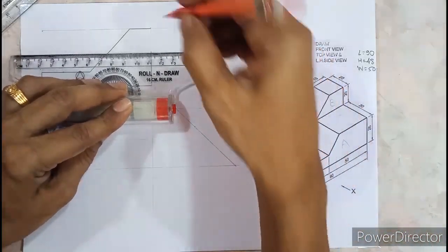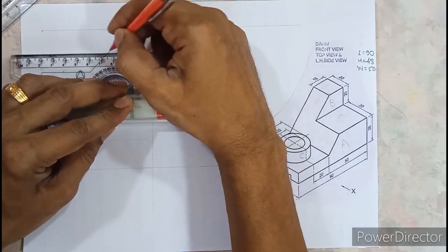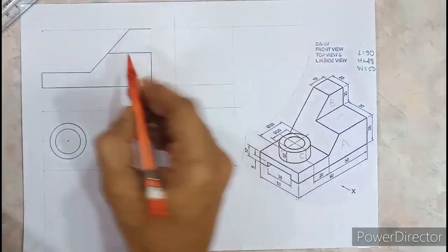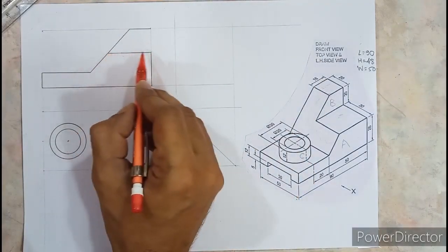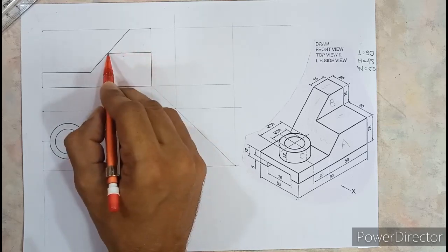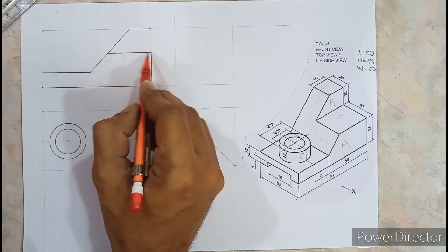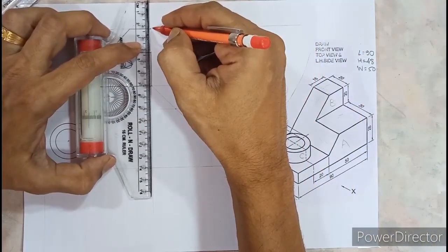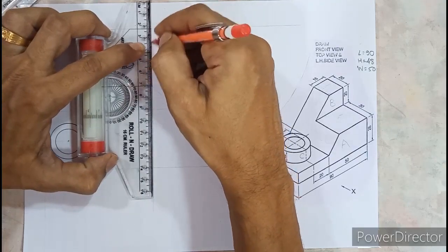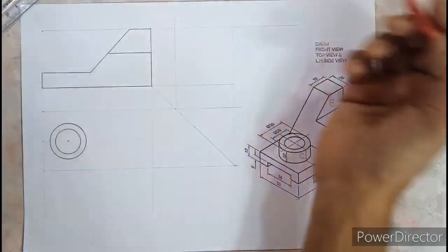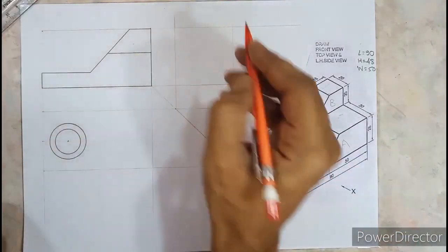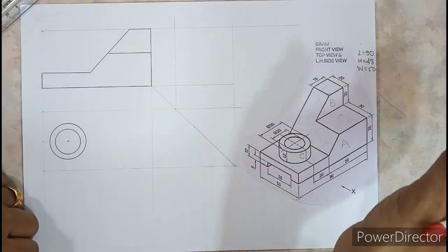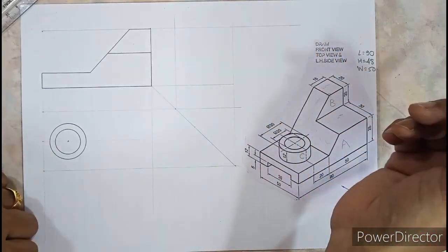If I extend this up and draw a double trace and draw a line like this, this length, which you can obtain only after drawing, you cannot obtain by any calculation, has been obtained now. So this 20 mm vertical edge can also be seen as a line. For that we need to close this here. So that is how surface A and B both are ready. I hope it is clear till now that in the front view the object appears like this.